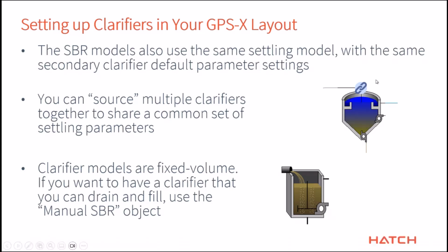Also, I would mention that all of our clarifier models are fixed volume. By that, I mean the clarifier will always assume that it is completely full and overflowing. So if you are in a situation where you would like to be able to pump down a clarifier as part of some simulation and then fill it up again, I would recommend using the manual SBR object, where you can do the same thing. It has the same clarifier model as this one does, and you can control it much better. You can have control over these pump connection points. You can empty it out and you can fill it back up again. The SBRs are designed to have variable volume.